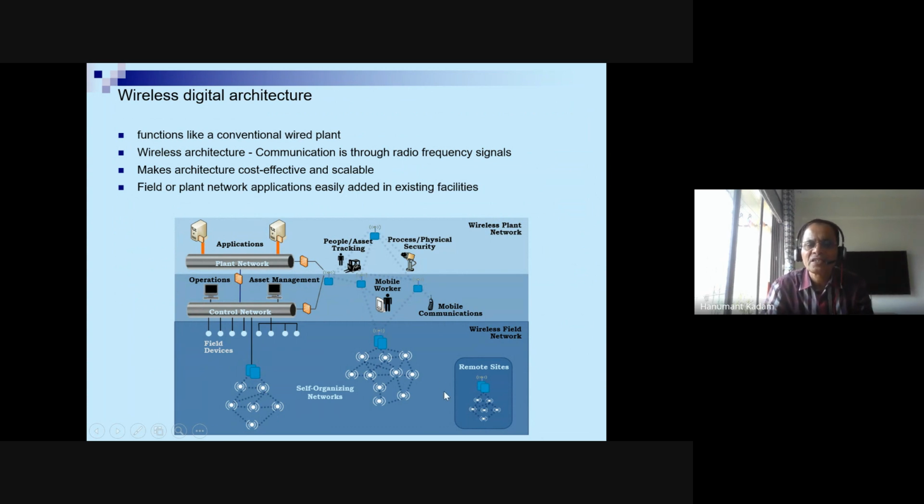You can see here, these are all your wireless transmitters. Here wireless transmitter, and these are the gateways, and through this it is getting connected through wire to the existing DCS network. Earlier wired devices are shown here. These are dotted. You can see here all wire transmitters or wire devices. However, these are all wireless transmitters through gateway. It is getting connected to the control room.